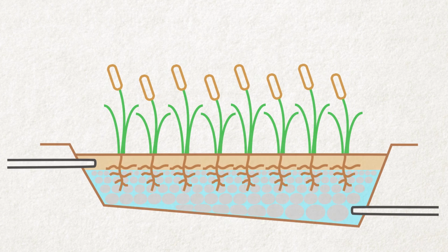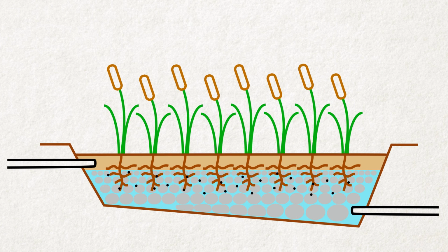The extent of nitrogen removal depends on the design of the system and the form and amount of nitrogen present in the wastewater. The overall success of a constructed wetland is limited by a variety of issues, which can show up during both the construction and the operational stage. For example, metabolic processes are vulnerable to changes in climatic conditions, and wetland substrates are easily blocked. Let's hear about some of the problems our interviewee has to deal with.